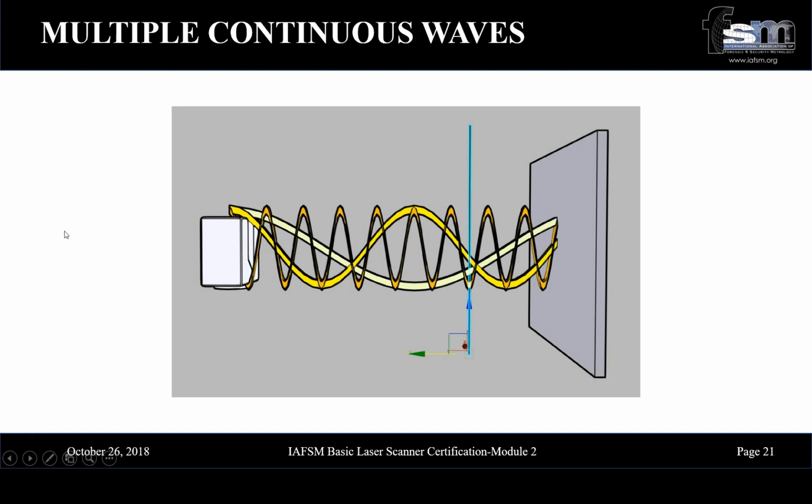When you combine multiple waves together, they form a unique combination of waves, and the scanner is typically set for or built around a specific distance. So if you were going to be measuring to 120 meters or 150 meters or whatever that might be, you would design the scanner so that the waves that are in that range coincide so that you don't get ambiguity. You can measure consistently within that range without any particular confusion.